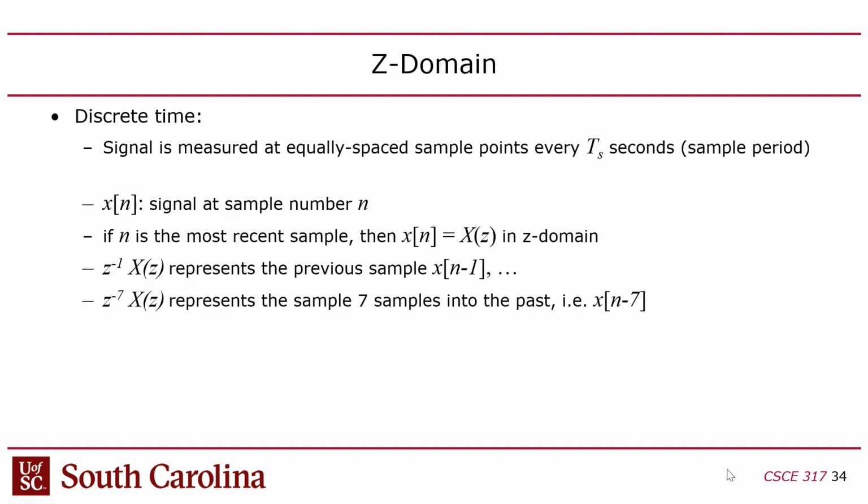But a processor can't do that. And you might say, wait a minute, but you simulated it in MATLAB. Yeah, because MATLAB discretized it, right? It's actually lying to you. It's doing a discrete simulation. So how does that work? Well, that's called the Z domain as opposed to the S domain. Z is a way to go from time domain to the Z domain. It's similar to going to the S domain, except it's discrete. But there's a few important differences.